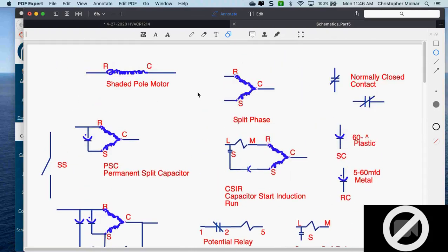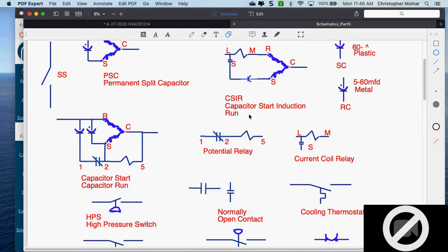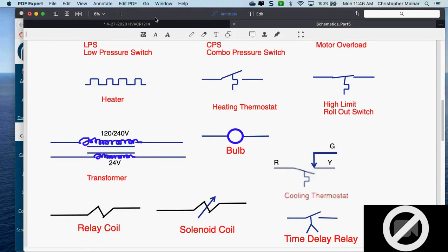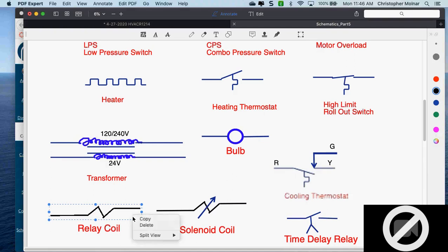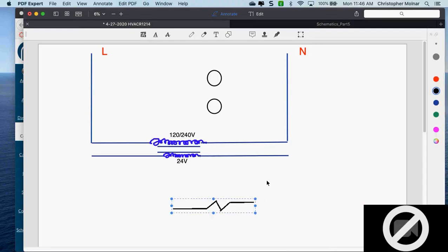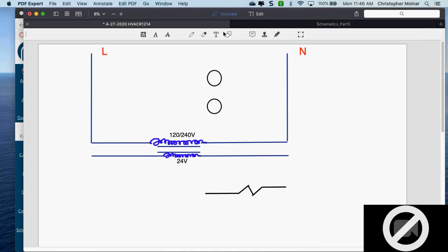Thermostat, right? Is that a load or a switch? Oh, sorry, no, it's a switch. So what do I have as a load? A heater on my low voltage side? A relay coil, did somebody say? Yep, I knew I heard somebody say relay coil. So I have a relay coil. Well, we know that's a load, so does it have to connect back to common someplace? Yes. So we connect that back to common.